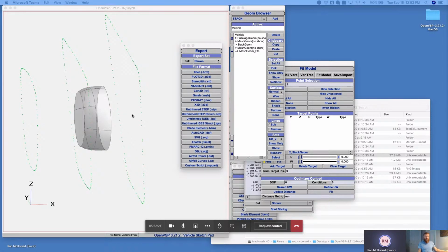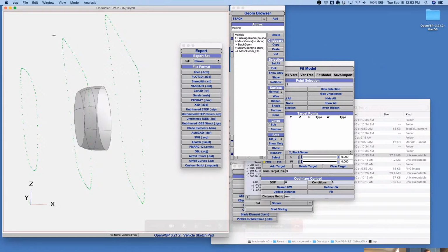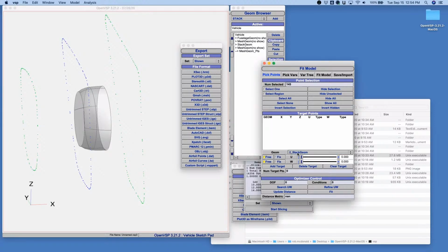All right. So I know this is jumping around a little bit, but I figured I'd just use these couple of minutes to keep everybody from having to stay late, if they wanted to. I can fix that problem. When I selected all these points, I went to associate them. Unfortunately, I chose to associate them with the original fuselage geometry, instead of choosing the stack, which is what I really wanted to match them to. So that's why it was taking a little bit longer than I wanted. And they all perfectly matched because they fit the geometry perfectly.